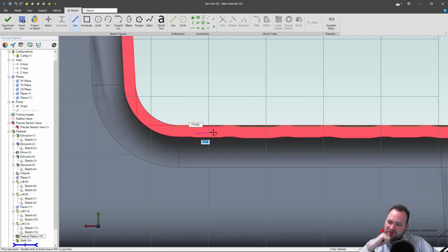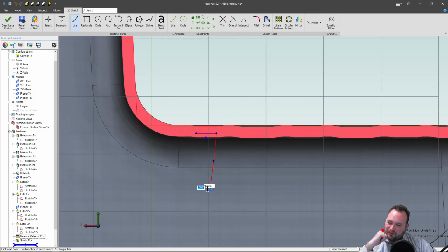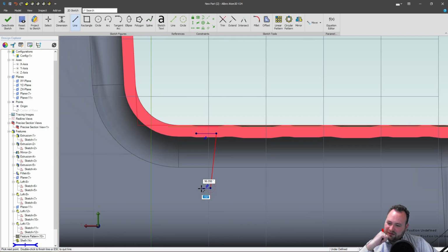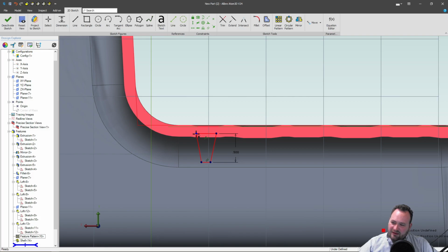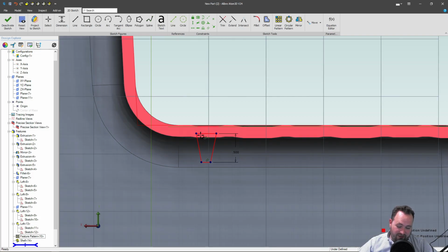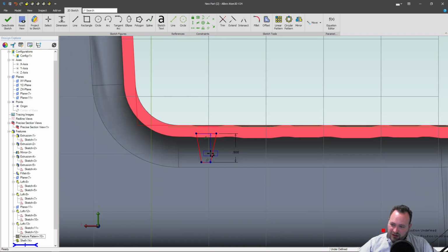Now, when it comes to injection molding, rib widths and heights matter. And they can mean the difference between success and failure. But also, injection molders will break the rules all the time. So these are the rules, but it's kind of a suggestion that your rib height is going to be 2.5 times your wall thickness. So our wall thickness of 0.2, we'll multiply that by 2.5. So 0.2 times 2.5, and then we have to have a draft angle, right? That's how you get the part out of the injection mold machine. So I'm going to say 4 degrees on that.